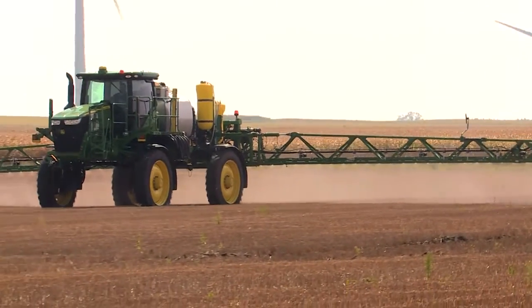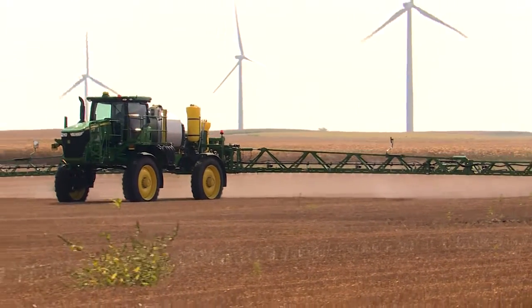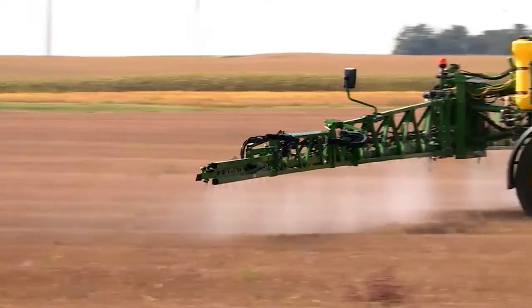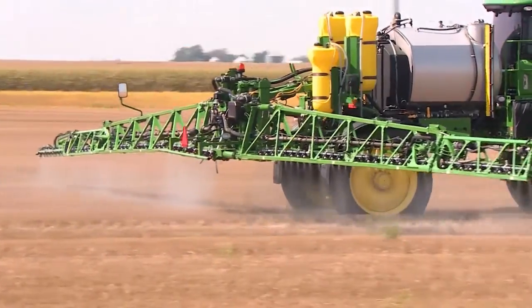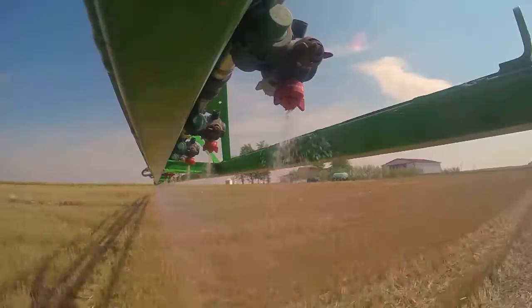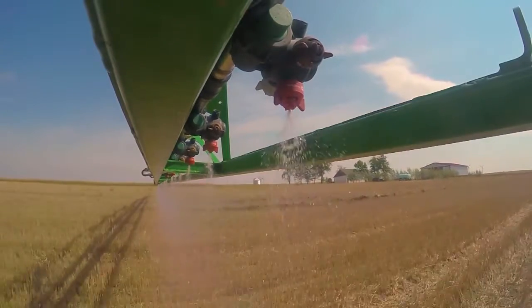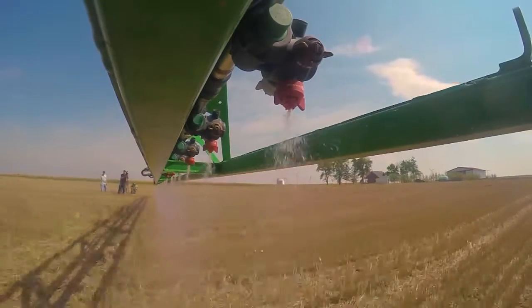The ground speed is based on the type of sprayer we're using and the terrain that we're going to be spraying on. So we already kind of know how fast we'll be going when we make that application. The effective sprayed width, the distance between the nozzles, is also set. So really what we're going to do is determine what flow rate we need out of our nozzle in order to apply a determined gallons per acre at a certain speed with nozzles at a certain spacing.